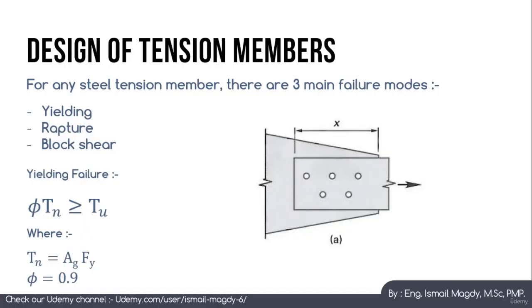For any steel tension member, there are three main failure modes. The first mode is yielding, and in this case, the failure happens in the steel section itself due to excessive tension force and due to reaching the yielding strength of the steel member. Second and third modes are rupture and block shear, and those failure modes happen in the bolted connection itself. Right now we are focusing on the yield failure. After that we will start learning the rupture and the block shear failure modes.